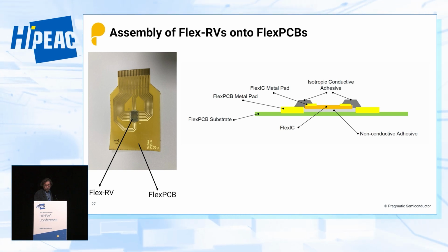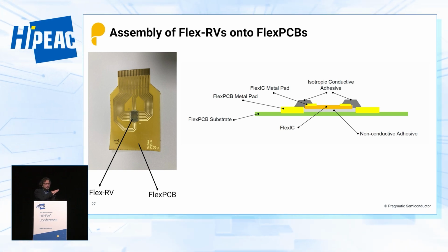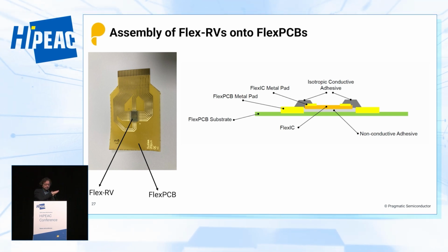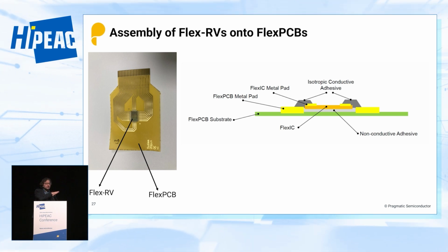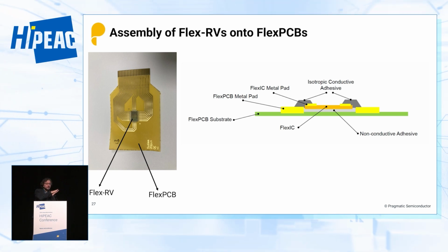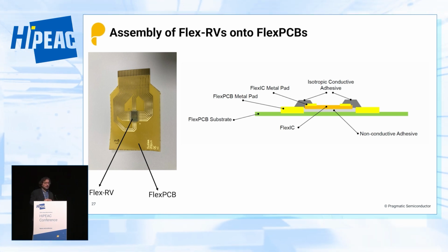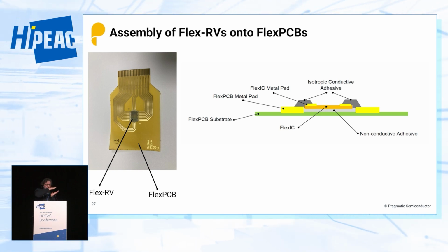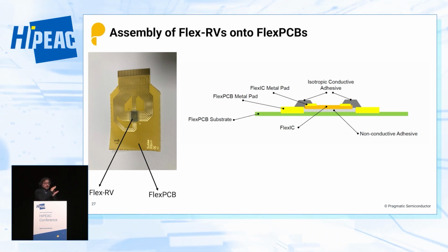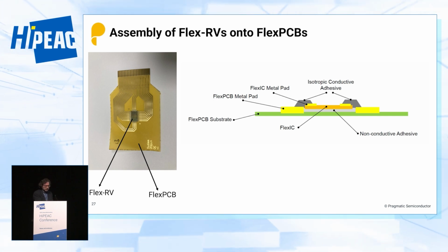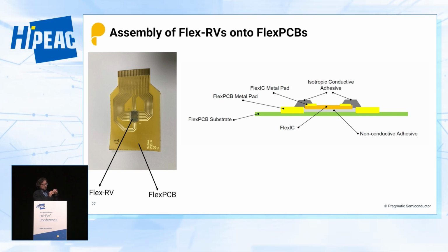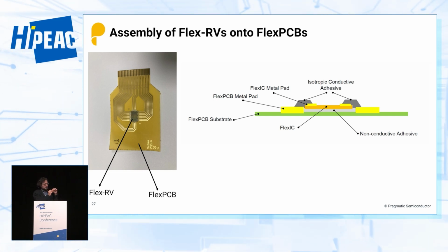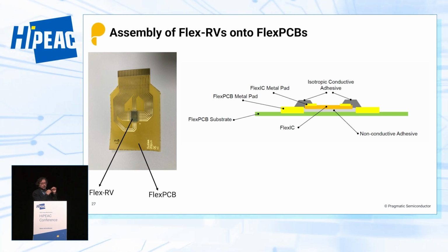What we are doing is placing the chip facing up, using some non-conductive adhesive. It's also different from a silicon chip package. So the bare die is face up. We don't do any kind of plastic packaging. This comes directly from the wafer, attached like this with a glue, but it's non-conductive.